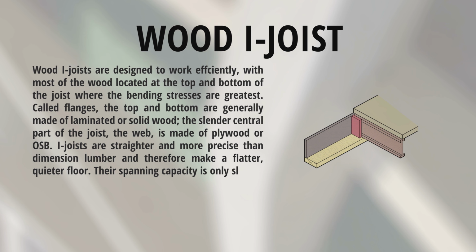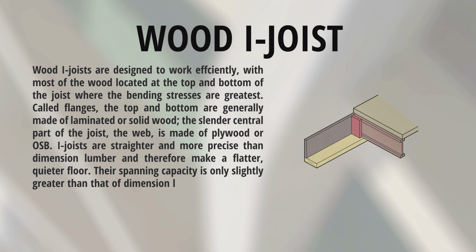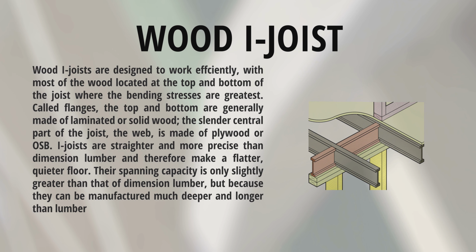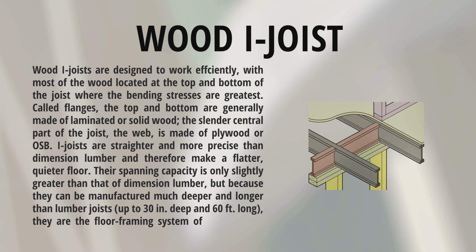Their spanning capacity is only slightly greater than that of dimension lumber, but because they can be manufactured much deeper and longer than lumber joists, up to 30 inches deep and 60 feet long, they are the floor framing system of choice when long spans are required.